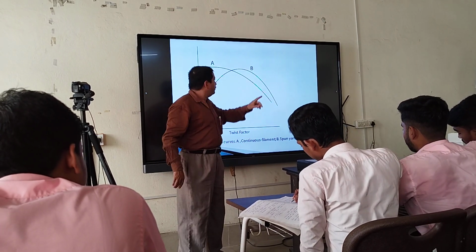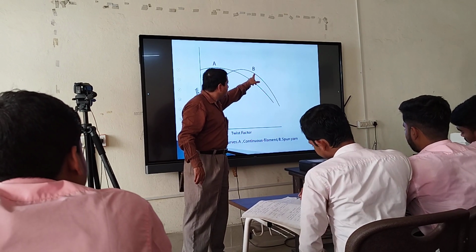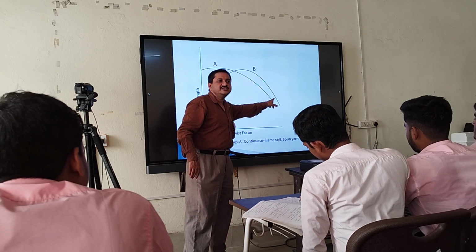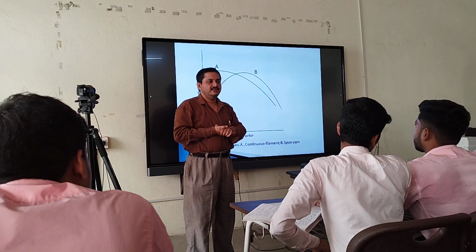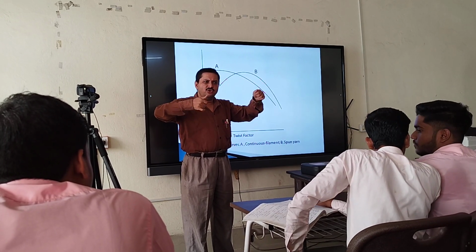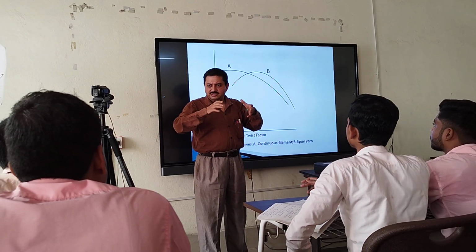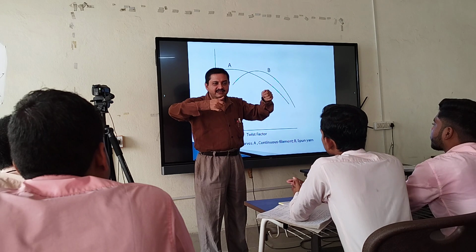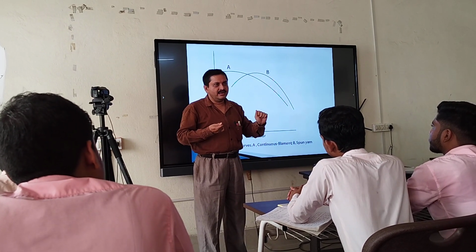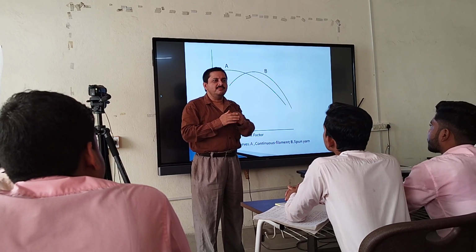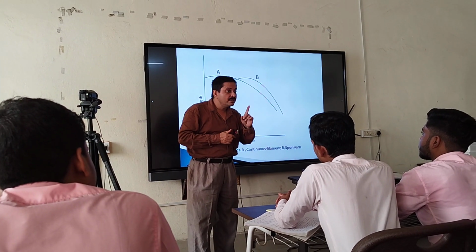After reaching this optimum twist and optimum strength, you observe that the strength of the yarn gradually reduces. Why this decline? Because as you apply the twist spirally, the fibers will be spirally bent, and ultimately a situation will come where surface fiber rupture takes place.